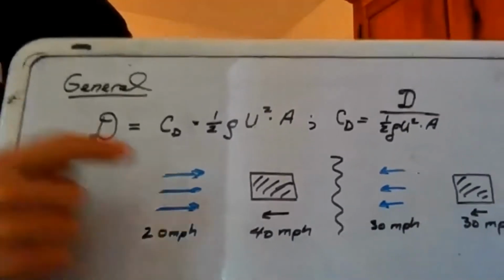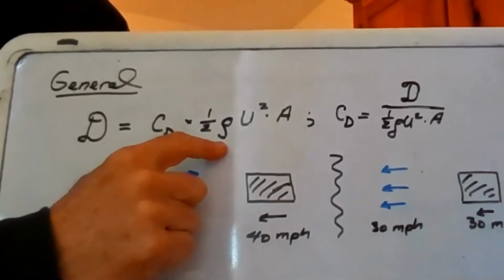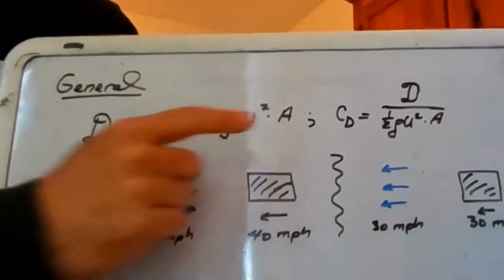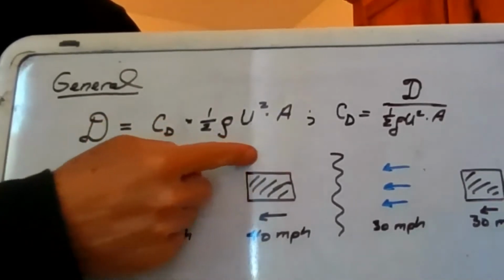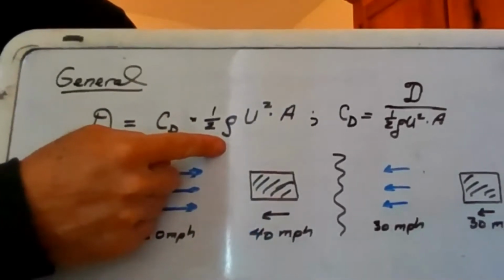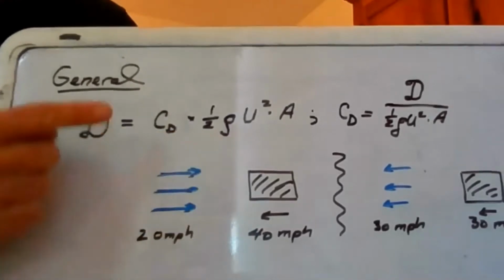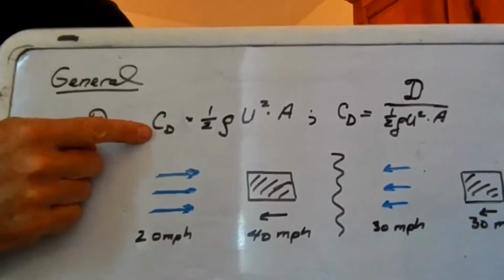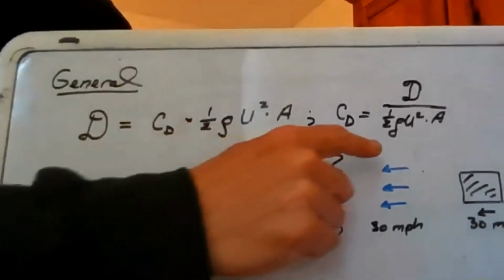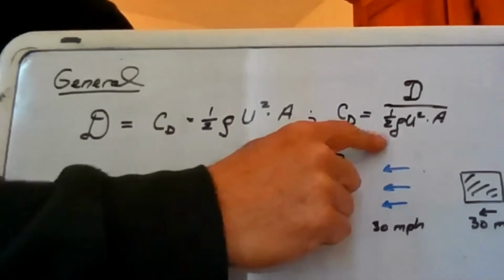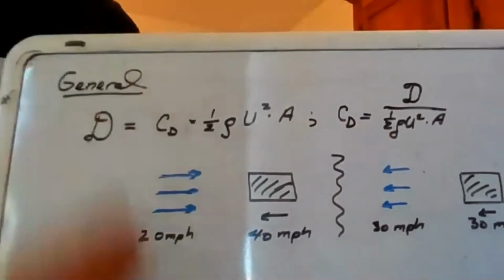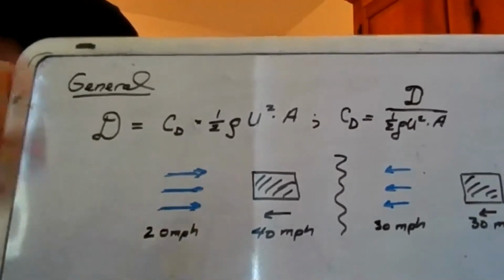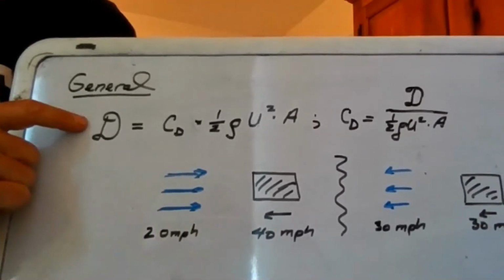To get the drag, we're going to take the dynamic pressure, 1/2 rho u squared, and some sort of area, but this portion of it works pretty well for blunt objects. We're going to have a modification term, CD, which is called the coefficient of drag. Your textbook and many textbooks present the basic formula that way. That is a good definition of what the coefficient of drag is. Often if you're doing design, the bottom line is, hey, what is the drag? So you're going to probably do this calculation.